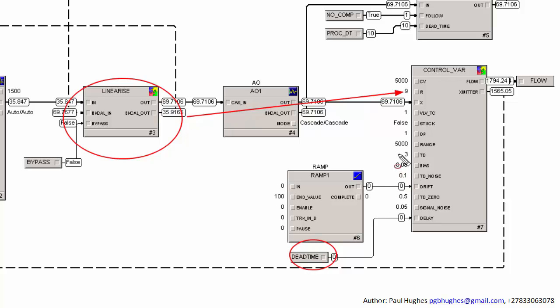And I've put the turn down to 3 to 1. And given the range of 5,000, that means below about 1,500 odd, or below about 2,000, we're starting to get some turn down noise, which is shown here. And we're going to get some turn down bias. In the previous videos that I've put together, this turn down effect was not totally representative of what we normally see. So I have added that characteristic into this model.